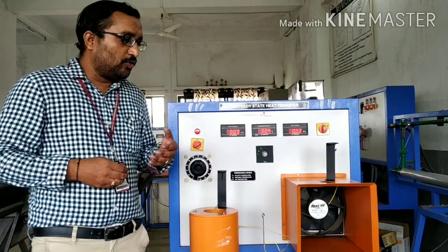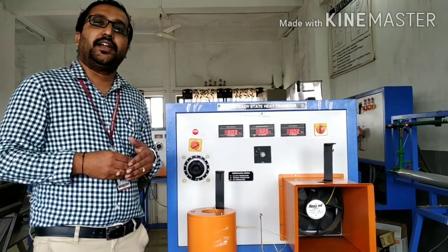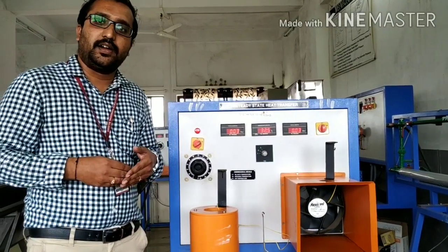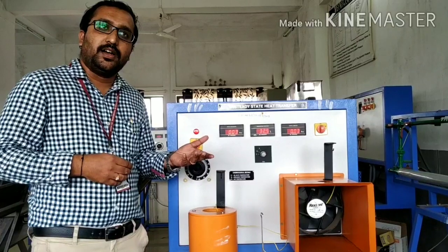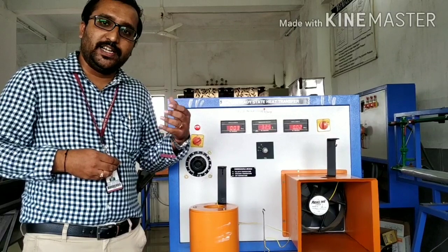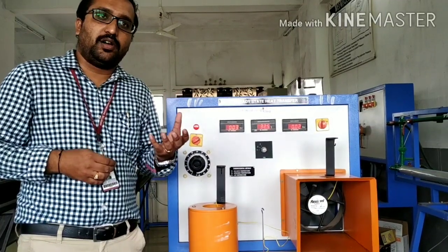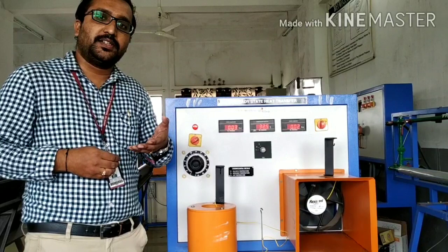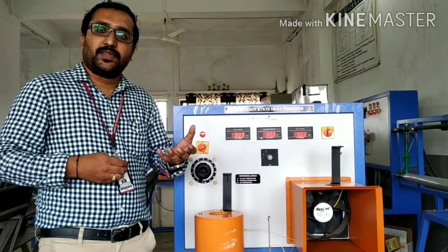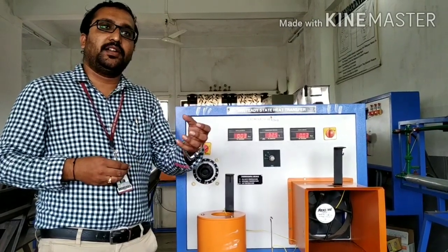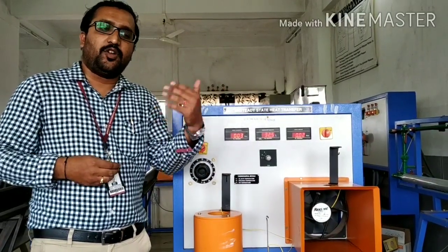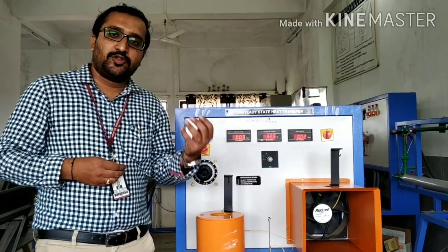To give one or two examples of unsteady state heat transfer in practical situations, let me give an example of a heat treatment process like quenching or annealing. In all of these processes, the ingot or the material whose properties need to be changed, we heat that material to a crystalline temperature, then we suddenly dip it into a fluid medium whose temperature is very low. Take for example quenching: we heat the material to a very large temperature, then suddenly place it into water or any given medium, or sometimes expose the body to air.